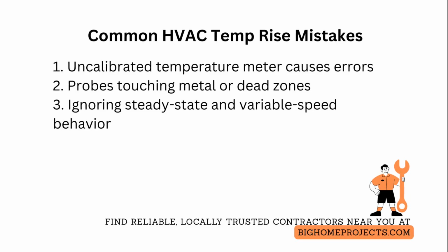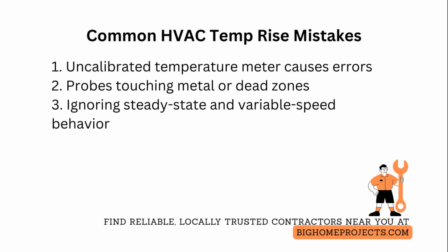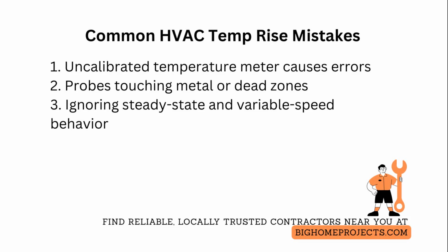Another of the top 3 is using probes that touch metal or are placed in dead zones, causing false low or high temperature rise and incorrect airflow CFM. Fix this by suspending probes in midstream with non-conductive mounts, taking multiple grille samples, and ensuring probes do not contact metal.